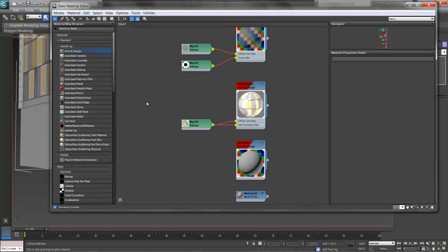What we'll do to start out is make some solid color materials, as these are very useful in a lot of places. For example, we need glass. We also need probably some chrome or something similar, and maybe a good white paint. We're going to use Mental Ray, and this scene already has Mental Ray on as a rendering engine. The reason for this is Mental Ray supports blurry reflections and bouncing light if needed.